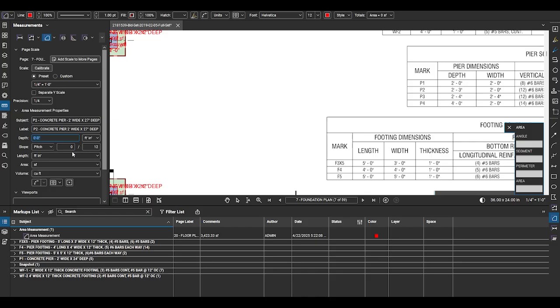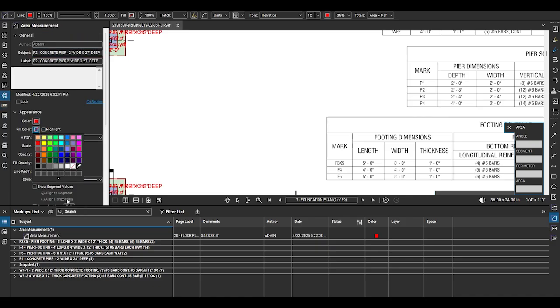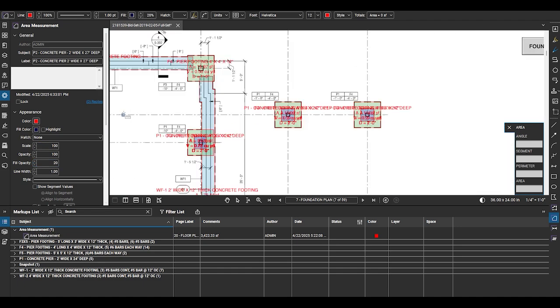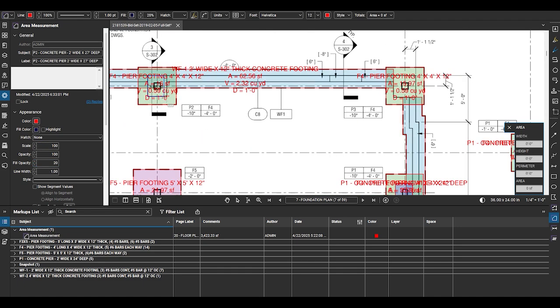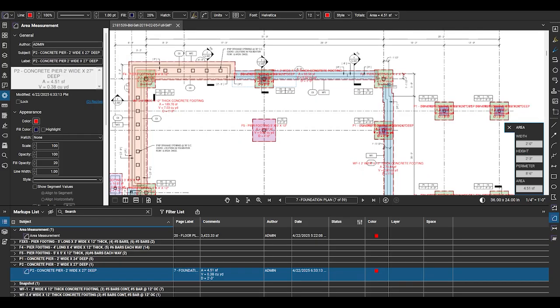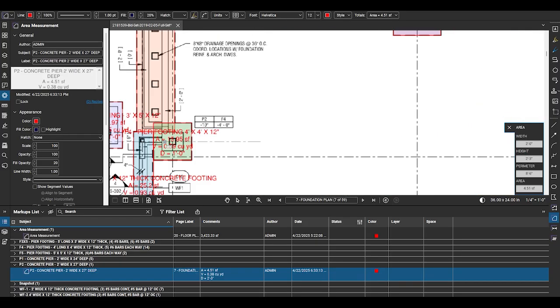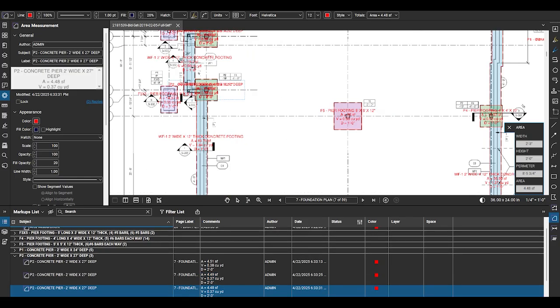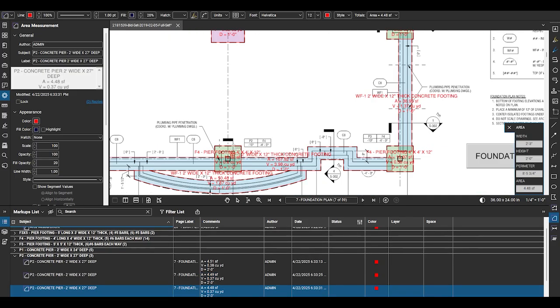Another item that's relevant to concrete and would normally be included in this takeoff is the anchor bolts associated with those columns. One additional item that would typically be covered in the concrete are the foundation drains shown in that WF2 footing at 36 inches on center. Again, this video was not a thorough breakdown of every detail. It's more to illustrate some basic elements across the entirety of a scope of work within a project and how to take this data into Excel to generate your dollar value costs related specifically to your takeoff quantities.